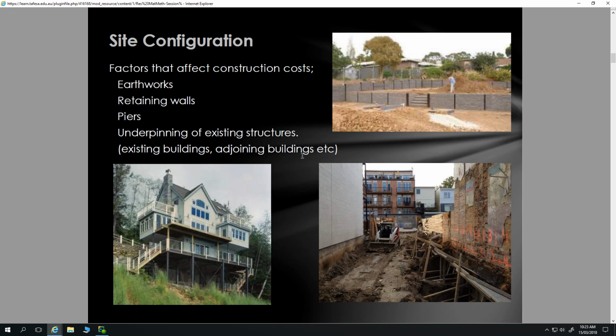one scenario I know of, I'm trying to think of the name, it's just near Walkerville, where the ABC building is. They're doing piers for a building. They were pouring concrete in, and they just kept pouring concrete because they hit some sort of cavity underneath. You run those sorts of risks with piers as well. So that's not an ideal situation.